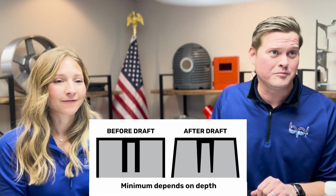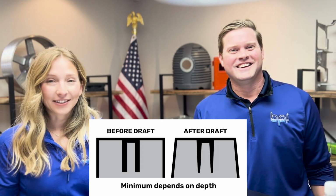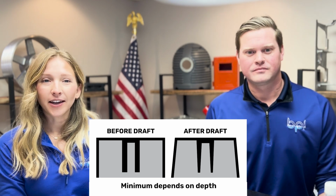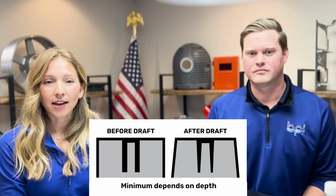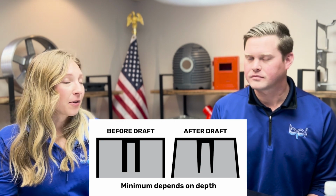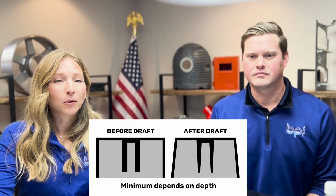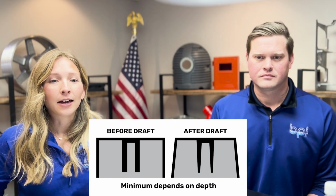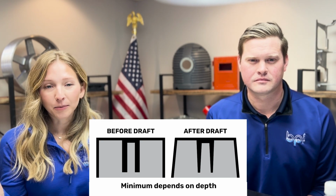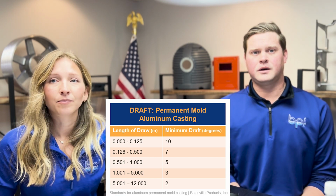Absolutely. Oh, here we go. Draft. Yes, you can never have too much draft, especially when it comes to gravity-fed castings. I would say, for the most part, depending upon the depth of the part, for example, shorter walls, you're going to need more draft. The longer the pull, the less draft you're going to need. And then you're always going to want to make sure your draft is moving away from your parting line. I don't know if there's anything else you want to add on that.